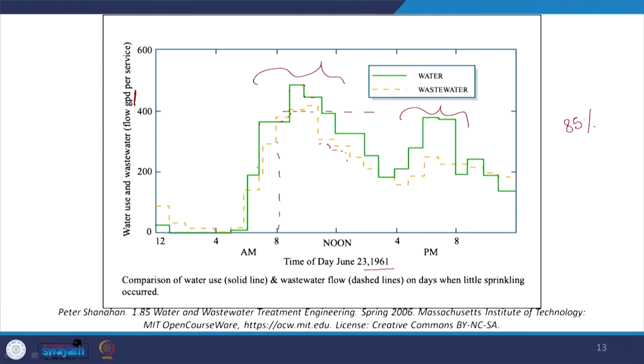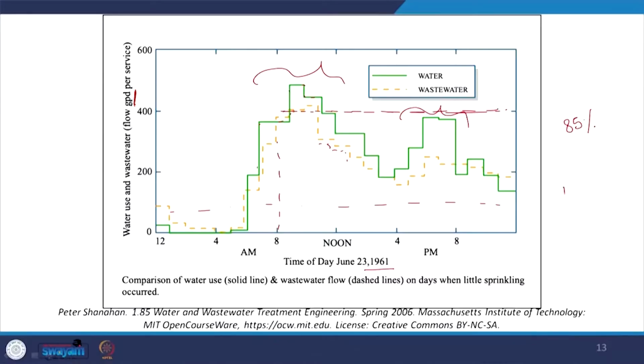For example, I can't just design for this particular peak flow rate, right. It is going to be uneconomical, and also even difficult to operate. But if I choose a remarkably low value, obviously during these high flow time periods, I am going to face an issue, right. So, you are going to typically look at the average while also looking at the peak factor. But in India people really do not look at peak factor, they look at average annual flow rates, or expected flow rates.